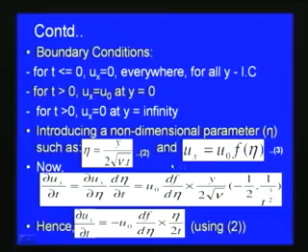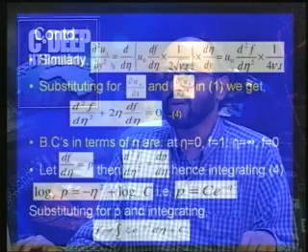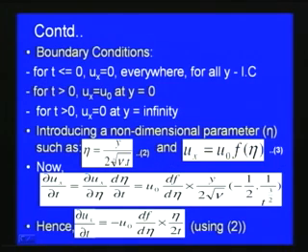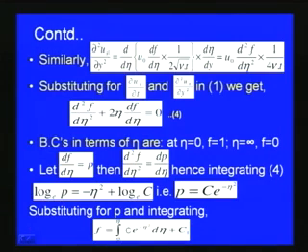So here we are transforming the system in such a way that we are trying to get a solution for this simplified form of the Navier-Stokes equation by using these boundary conditions. Similarly, we can write del square ux by del y square is equal to d by d eta of u0 df by d eta into 1 by 2 square root of nu t into d eta by dy, that is equal to u0 into d square f by d eta square into 1 by 4 nu t. So we can now substitute for these approximations with respect to the introduction of eta. We have written del ux by del t and del square ux by del y square, so we can put them back in equation number 1.